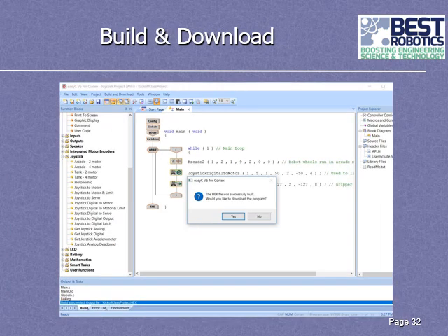When you hit the build and download, it will start running, and down in this window here, the output and task, you'll see lines will be appearing here. This is the build process occurring. If there's an error in the build, it will occur here, and then of course you have to look at the specific error to try to figure out what exactly it is that went wrong.